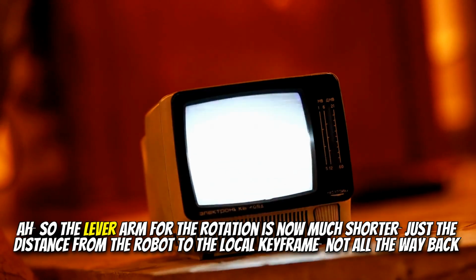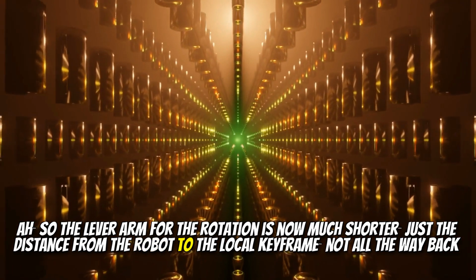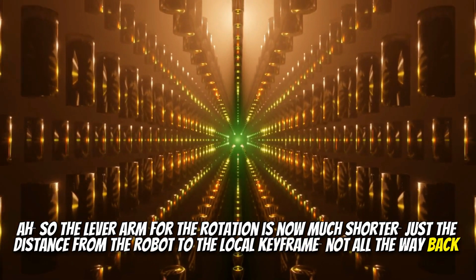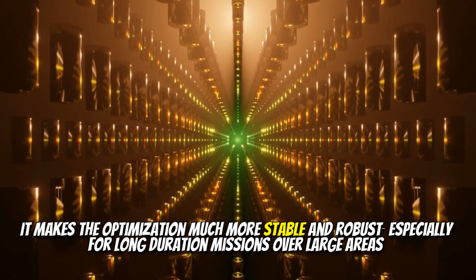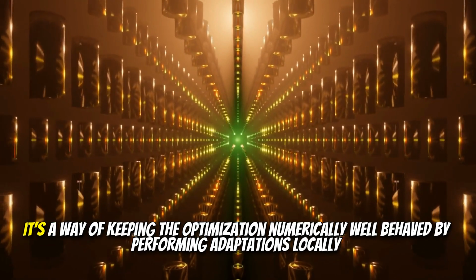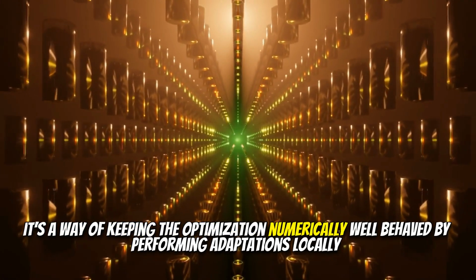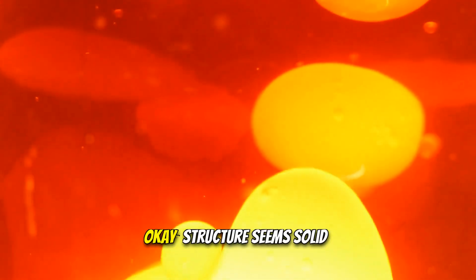Ah, so the lever arm for the rotation is now much shorter, just the distance from the robot to the local keyframe, not all the way back to the world origin. Exactly. It makes the optimization much more stable and robust, especially for long-duration missions over large areas. It's a way of keeping the optimization numerically well-behaved by performing adaptations locally. That's quite elegant. Okay, structure seems solid.